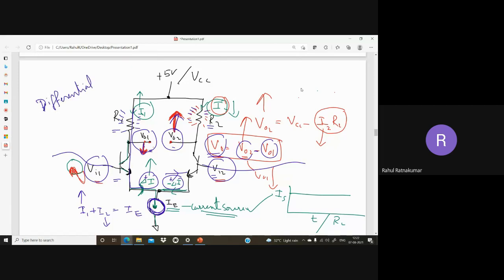This is a differential amplifier. This is one of the main first stages of the op-amp. After the differential amplifier, we have other amplifier gain stages. We just improve the gain. The last stage is just coupling or output impedance, the common collector stage, for matching the impedance to make the output impedance 0.